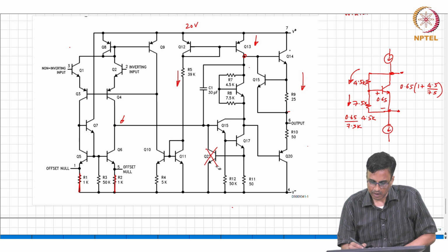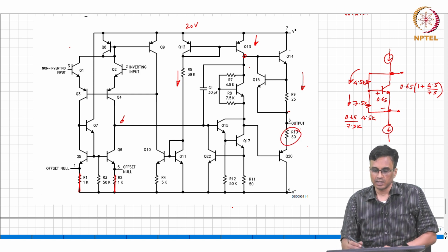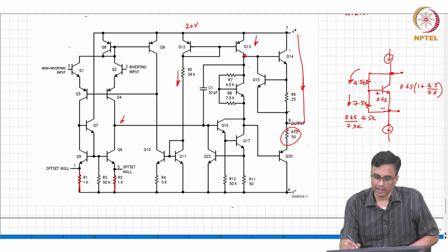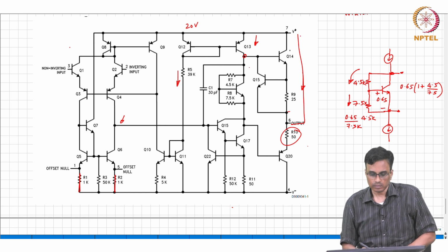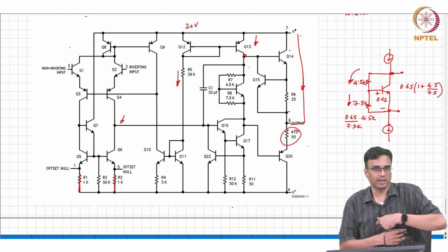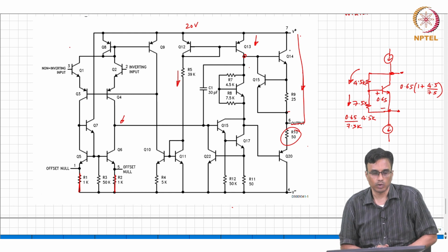Likewise, for the PMOS transistor, first of all, there is a resistance in series to prevent somebody from connecting this directly to VDD. That would simply blow the device.